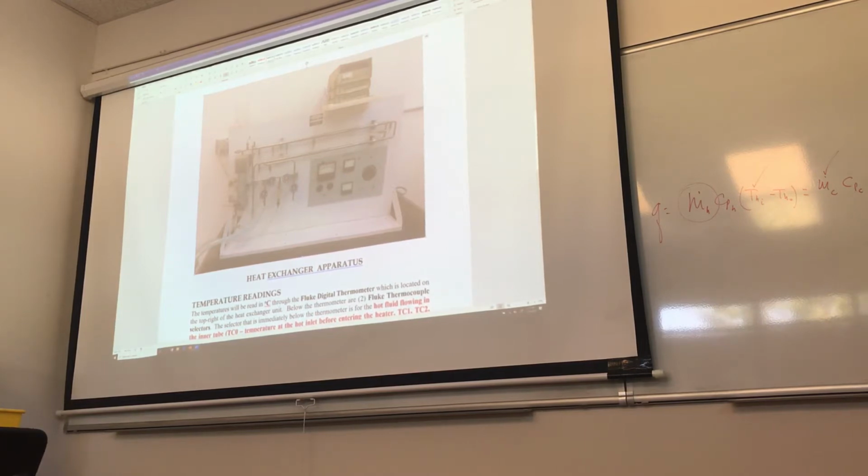So what happens to the fluid that comes in? If all these valves are closed and the only one that's open is this one, the fluid comes in and goes this way, and comes back that way. You see, now it's running in the same direction as the hot fluid, except that the hot fluid is running in this interior pipe that is really tiny, whereas this one is a thicker pipe. Why? Because it has a jacket, an annulus around it, where the cold fluid is running.